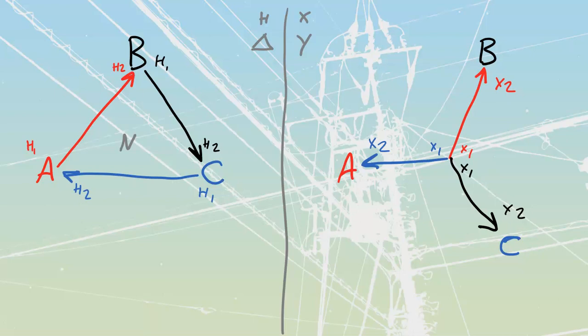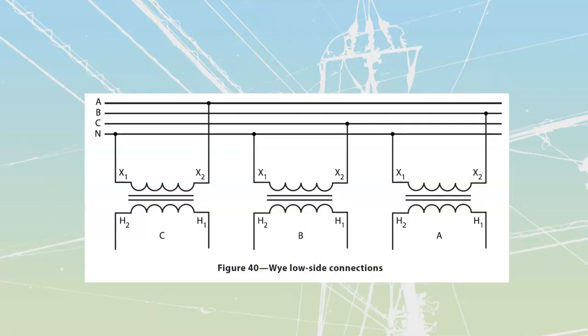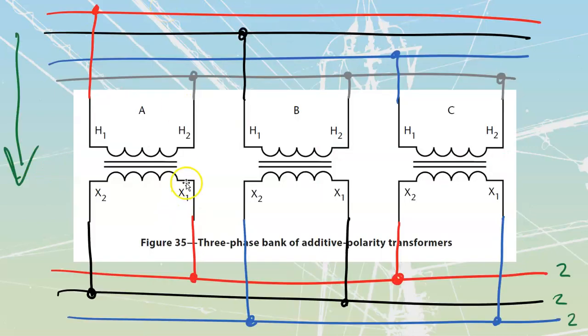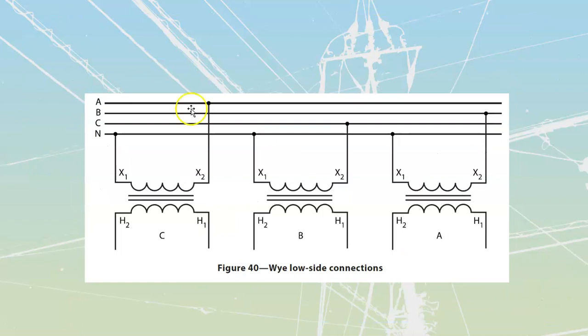Okay, we said that we were going to be feeding in on the low voltage side, the X, going from a Y. Feeding in on the low voltage side, we're stepping up to a delta on the other side. So we're going to start by making all of our connections onto that same one. They don't give me a blank set of transformers to draw over top, so we're just going to work with the ones that they have over here. But it's the same connections that we're seeing. We're going to start with, actually I am going to grab this one over here. 2 seconds. We're just going to throw in a new slide. It's just better for us if we draw the whole thing out there.